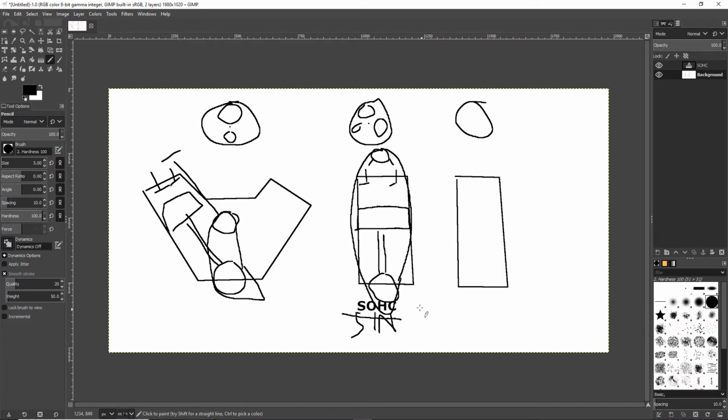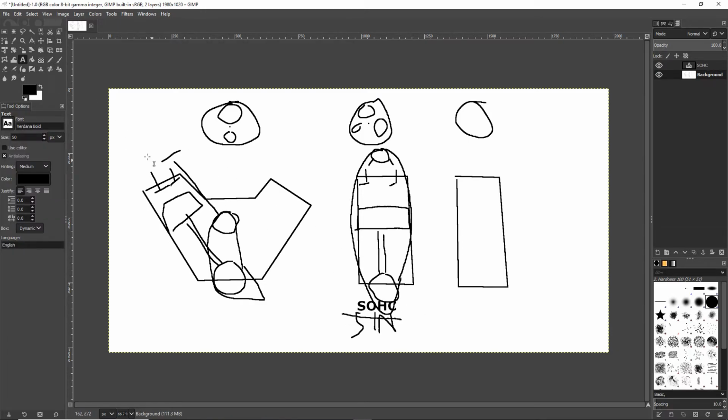On the side of a Civic is where you saw SOHC, single overhead cam, and I can't make this any simpler. The pushrod engine, where's the cam? It's in the block. Single overhead cam, where's the camshaft? It's over the cylinder head. How many? It's one, single.